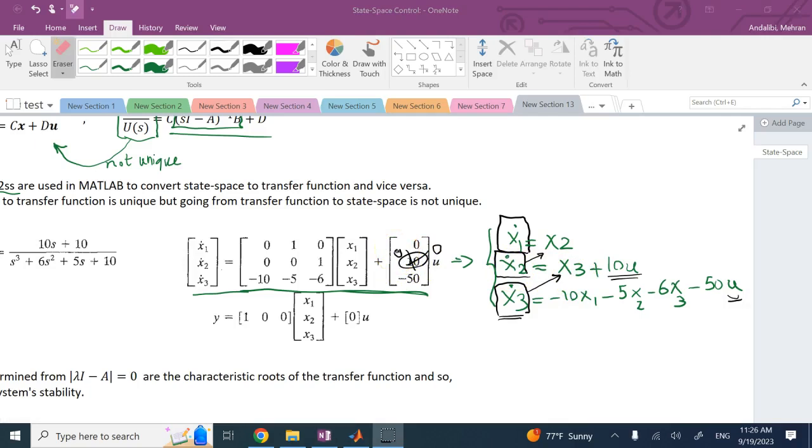Okay, now you might ask, could you do something to this A and B matrix and make it uncontrollable? Well, let's see what we can do. For example, let's say here, if I bring that negative 50 to here, up here, so I make this guy negative 50. Okay, right? So x1 dot becomes x2 minus negative 50 times u. So u is directly affecting x1. Okay. Also, u is affecting x2. Right?